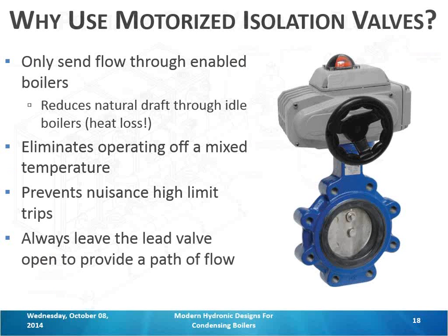When it gets down small enough, say 5 degrees, go ahead and close that valve because you have pretty much all the heat out of that heat exchanger. And you're just maximizing the amount of heat from the fuel you burn that you're putting into your system. Just one of those little tricks that you can do versus just throwing 5 minutes at the valve and calling it a day.